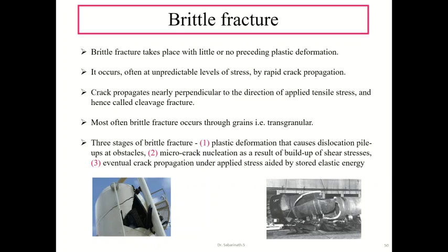So the three stages of brittle fracture are: first is plastic deformation that causes dislocation pile-ups at obstacles, next is microcrack nucleation as a result of build-up of shear stresses, and third is eventual crack propagation under applied stress aided by stored elastic energy.